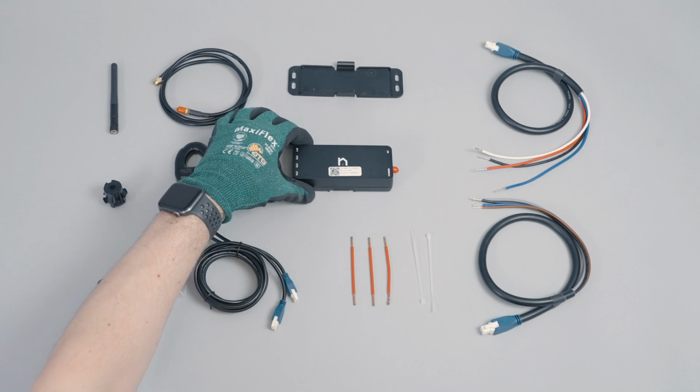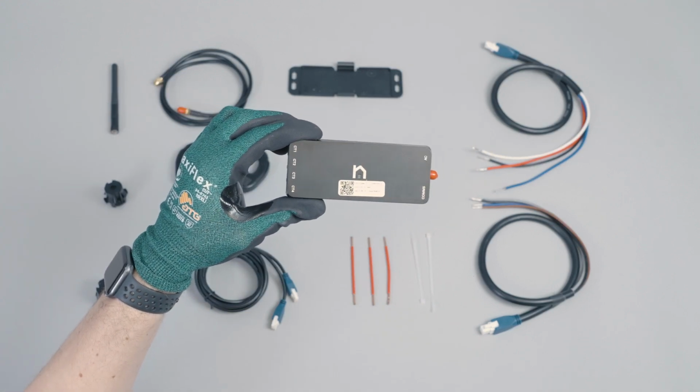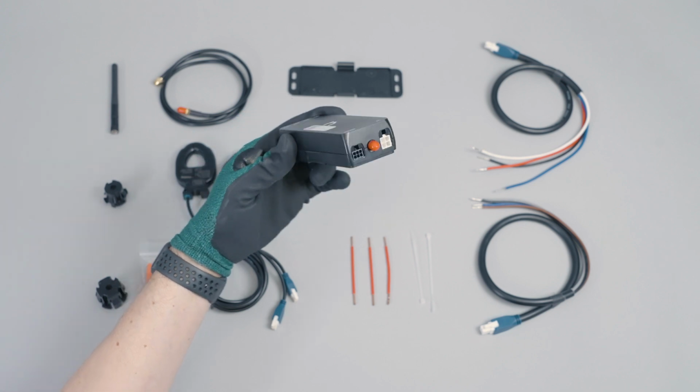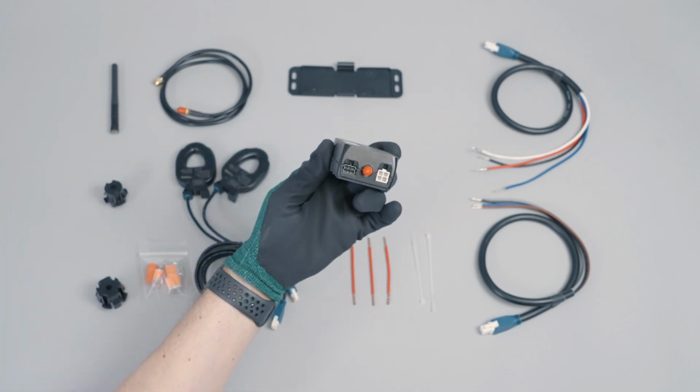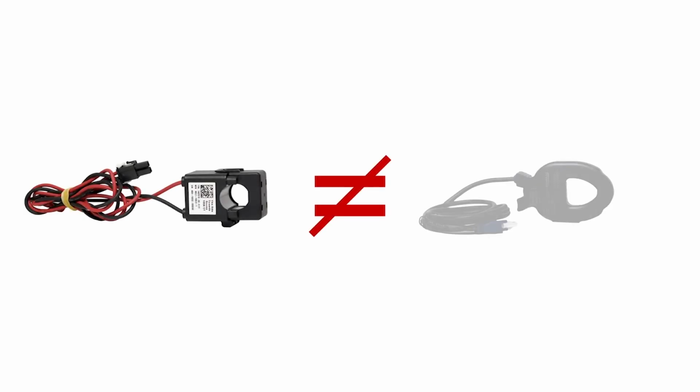Install a remote Neurio meter if the equipment that needs to be monitored exceeds 100 amps, or if distance, obstructions, or inaccessibility prevents the use of auxiliary CTs. Note that auxiliary meter equipment is not compatible with remote metering equipment. Auxiliary CTs only work with meter Y, and remote CTs only work with remote meters. Do not splice or use Y splitters to combine different types of CTs.